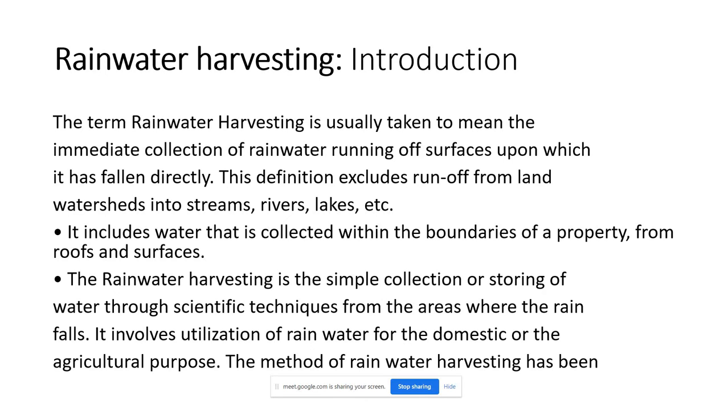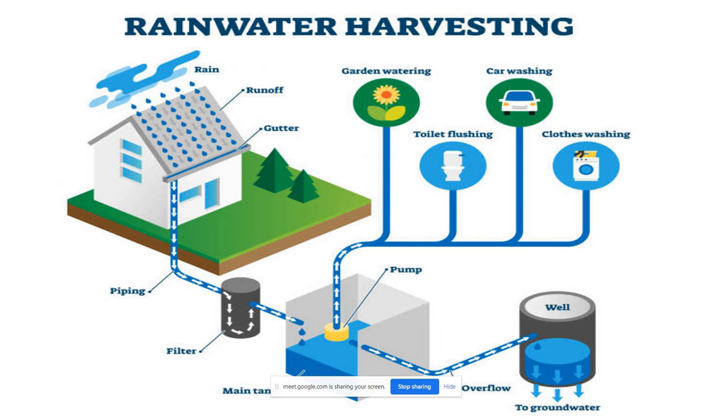Types of rainwater harvesting: roof water harvesting and in-situ water harvesting. Roof water harvesting includes collection of the precipitation falling onto the roof or terrace of a building and storing it in a sump at ground level, or directing the water onto the ground directly after passing through filter media to recharge the groundwater, which is depleting day by day due to overuse.